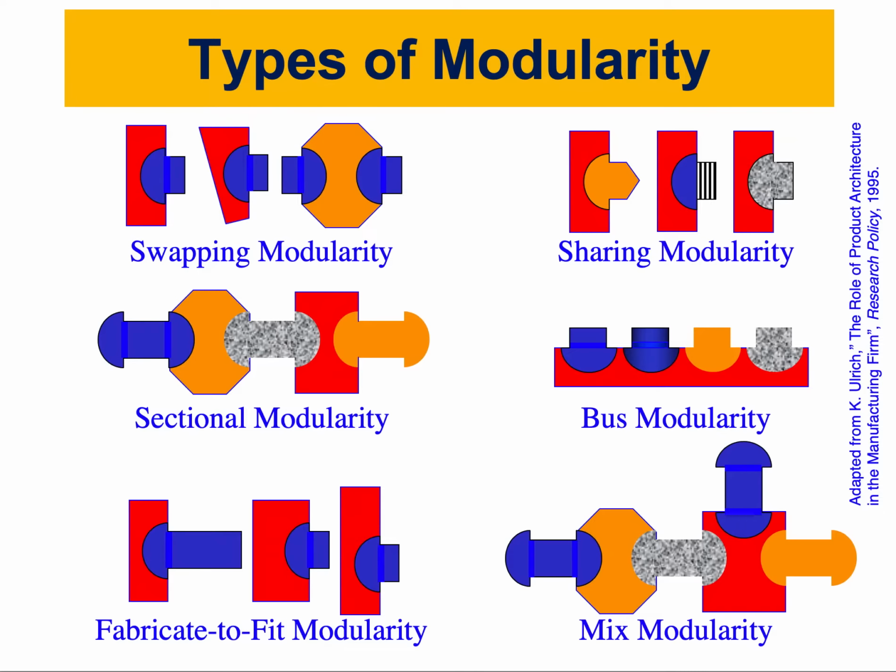In a quick review, modular architecture is one in which a functional element of the product is implemented by exactly one physical chunk. So each chunk is doing one task, one function. To recall also, a chunk is a collection of components or parts. So we are dedicating a chunk for a function, and this way we have few well-defined interactions between different chunks.